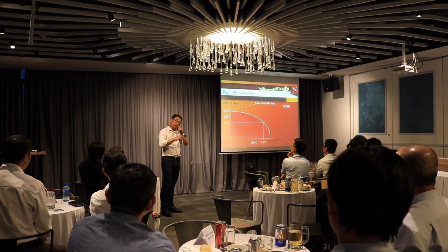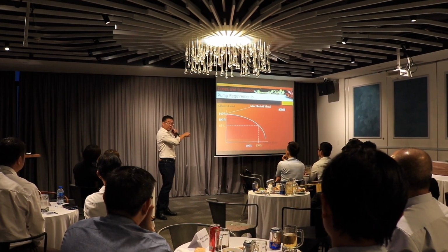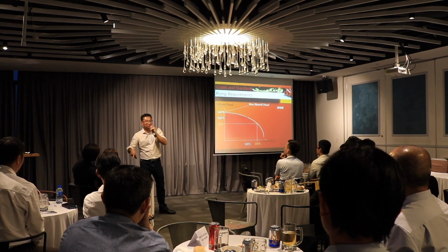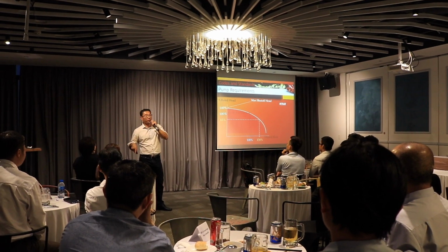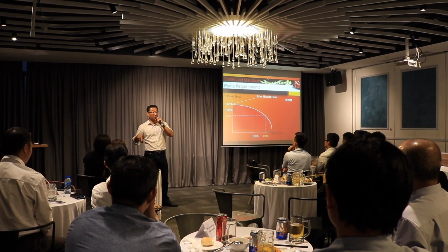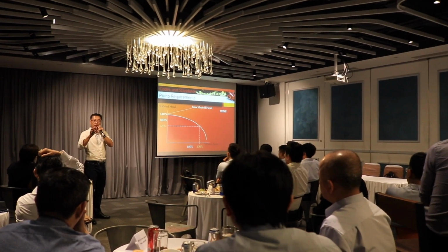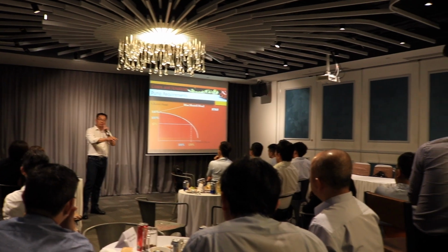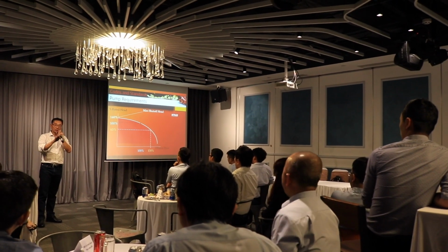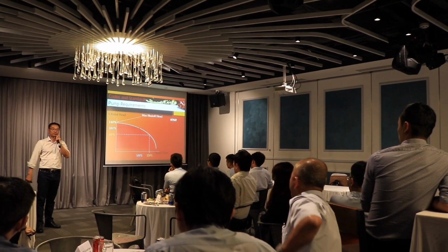So a UL pump that passed has to meet all this plus the NFPA 20. The net positive suction head must be able to reach 3.8 meters at 150%. Then this pump is UL listed according to NFPA 20.